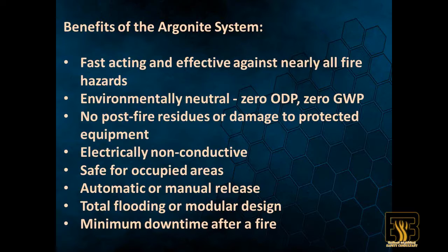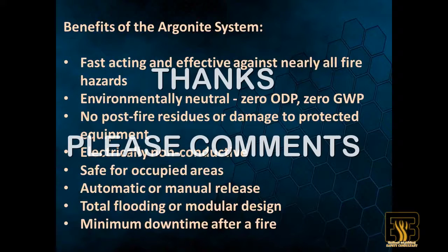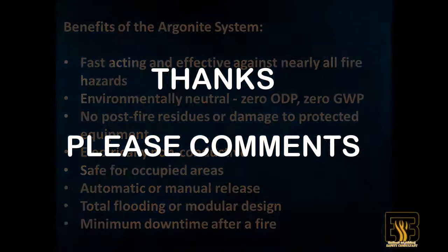Benefits of the Argonite system: fast-acting and effective against nearly all fire hazards. Environmentally neutral, 0 ODP, 0 GWP. No post-fire residues or damage to protected equipment. Electrically non-conductive. Safe for occupied areas. Automatic or manual release. Total flooding or modular.